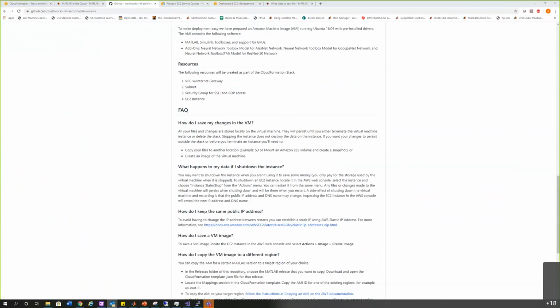Because at the FPGA level, we have eliminated any operating system. We have eliminated all those overheads about transfer of the data between the memory and the logical unit and stuff like that. It's all field-programmable gate arrays, so it's hardware logic that is really, really fast. Especially when it comes to DSP and signal processing kinds of applications, FPGAs are very powerful and very fast.